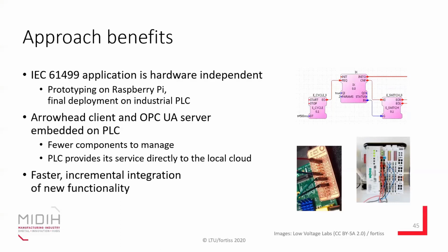And of course, what we're showing with all this is that a seamless integration of PLCs into service-oriented architectures is possible. And of course, service-oriented architectures allow making system components more independent from each other, to decouple them along clearly defined interfaces. And this in turn means that it becomes easier to manage the overall complexity of the system and maintain it over its lifetime. Where maintaining, of course, means adding or modifying functionality, just as the time management, this new time measurement that we were adding in our example here.